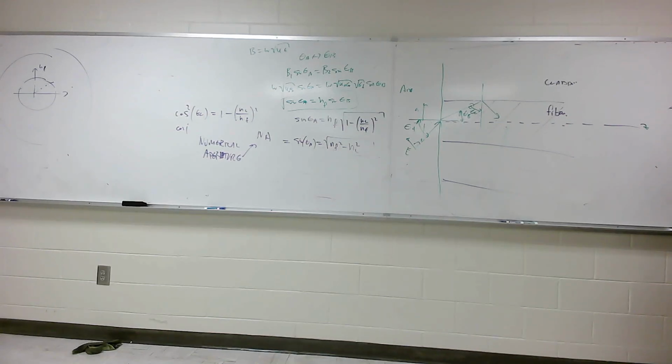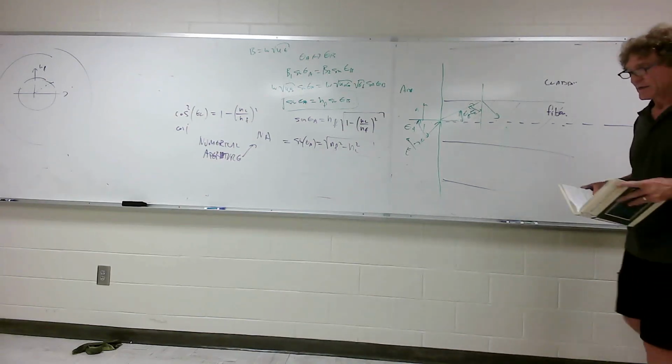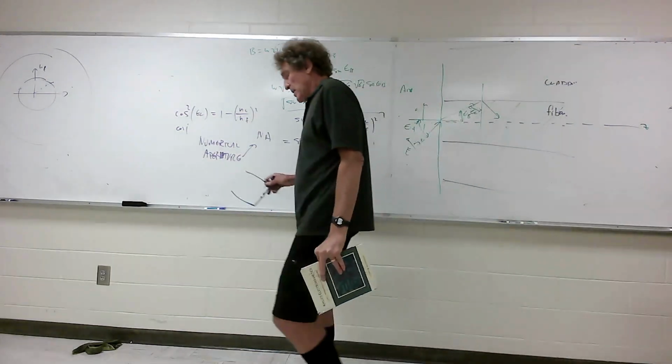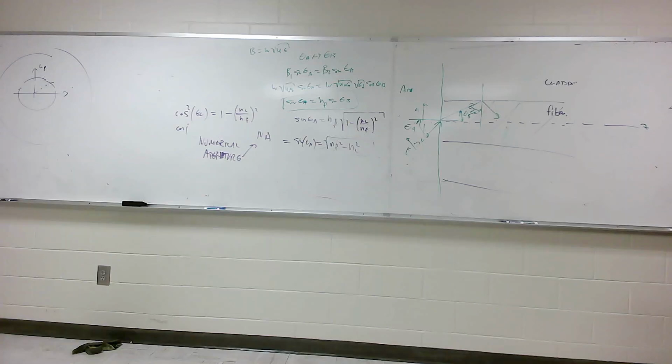You can't even solve the equation to get this. But if you look at equation 7.103, I won't put it the way he does it, there's one critical thing. You know how for the TE10 waveguide, getting that 10 cutoff frequency is the key thing. It's essential that you know that, because you have to operate above that, and then the 2.0 is just twice that. You with me on this, class?